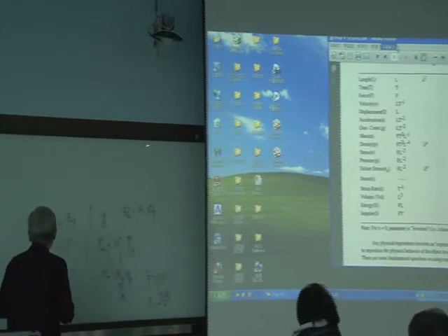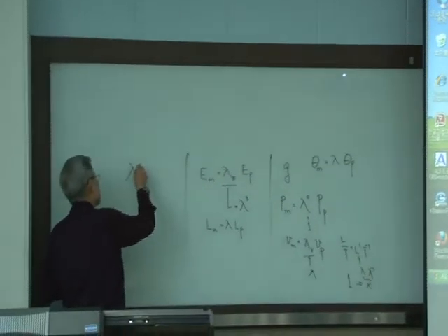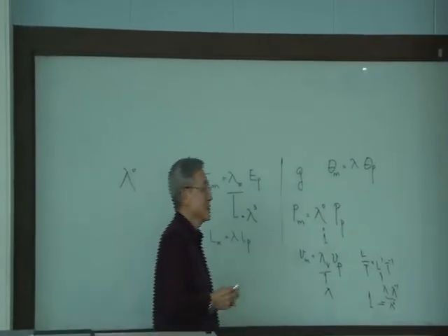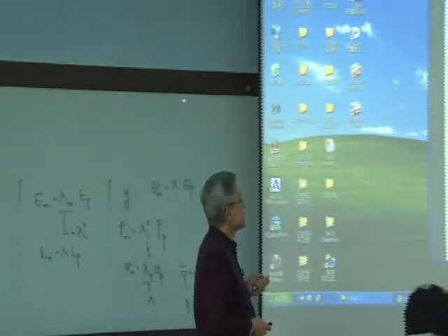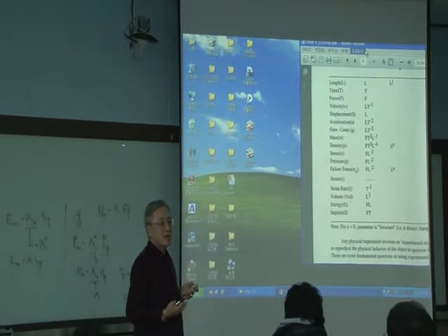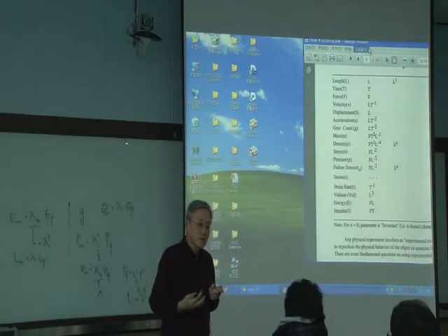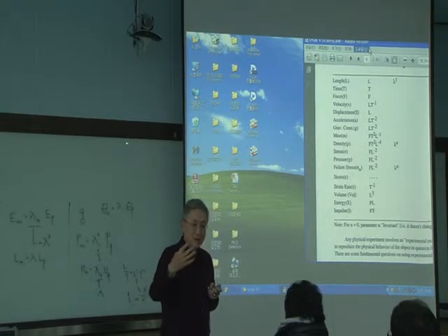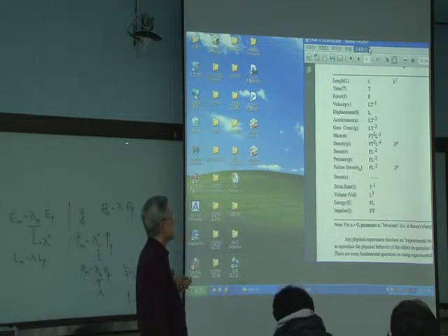I know what you mean, lambda to the 0 power, but just call it 1, right? What does it mean? The velocity measured in the model testing is equal to the velocity that could occur in the prototype. Beautiful, beautiful result.